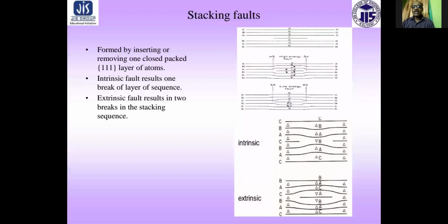Next is stacking fault. Before we discuss stacking faults, first we need to understand what stacking is. It is found that lattice structures are described by the stacking of identical planes of atoms one over another in a definite manner.